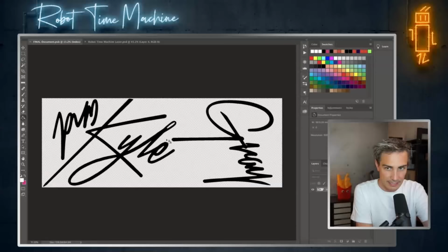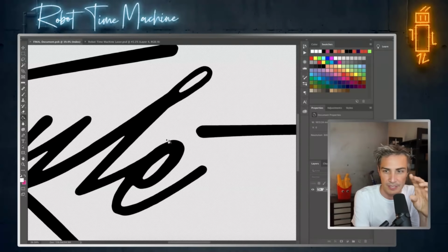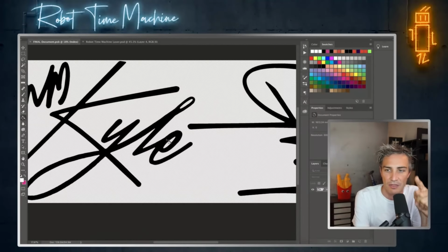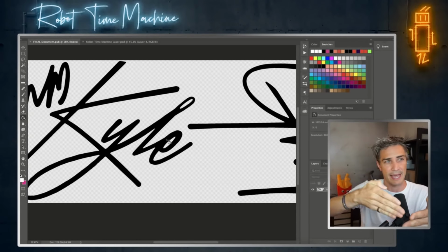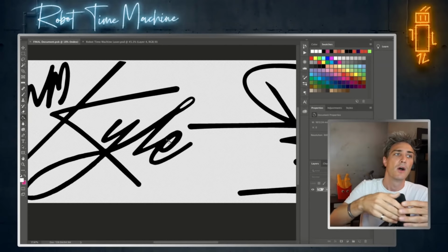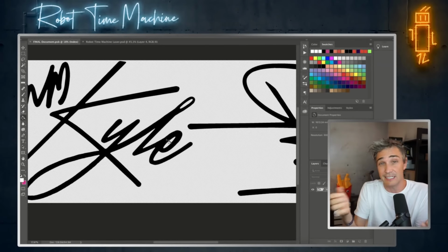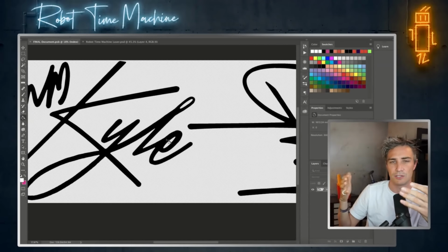One of the things you will have noticed is that you don't actually use these bold shapes. I'm just showing you here so that you can see what the file looks like. That's not the file that you actually send to the printer. You create outlines, and then depending on the setting of the printer, if the line is red, that means use 100% intensity, or if the line's green, something else. There are different ways to set it. You can set it to thickness, or if you just want to engrave, you can set it to engrave and so on.